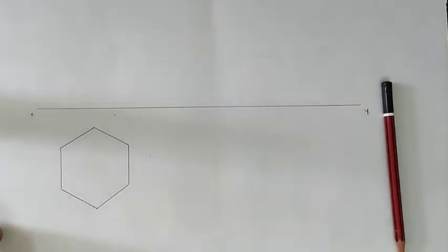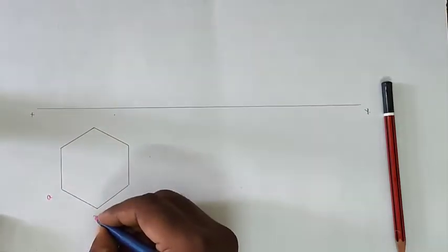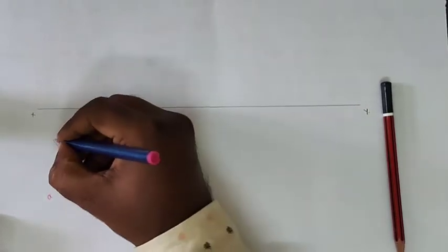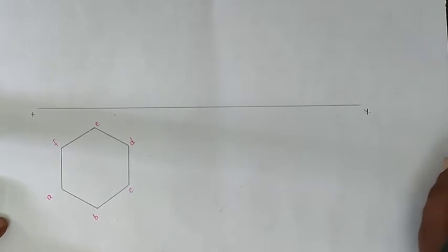So this is the top view of our diagram. If the edge is given, the hexagon is drawn this way; if a corner is given, the shape of our hexagon should be different. So this is the pyramid. We give only one type of numbering: A, B, C, D, E and F. We need not draw another, because it is only one base.